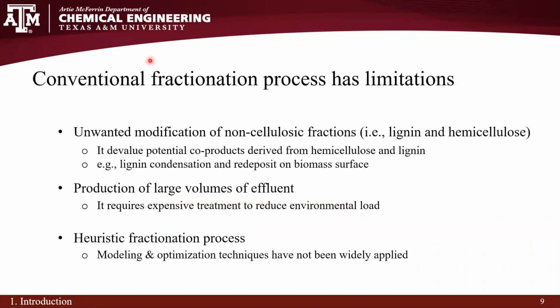Likewise, the conventional fractionation process has limitations, which result in unwanted modification of non-cellulose fractions, and this kind of unwanted modification devalues the potential co-products derived from hemicellulose and lignin. And also, due to the use of strong reagents, it produces a large amount of effluent, which requires expensive waste treatment to reduce the environmental load.